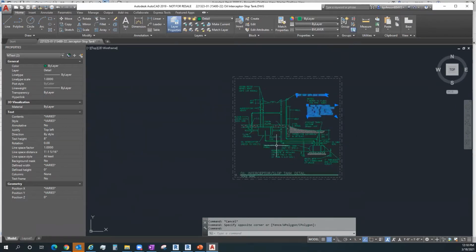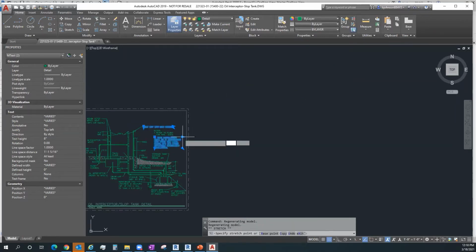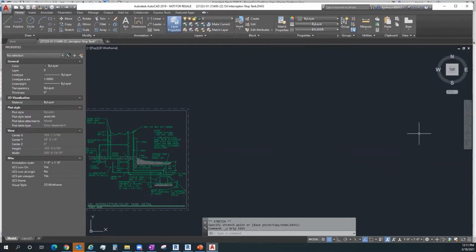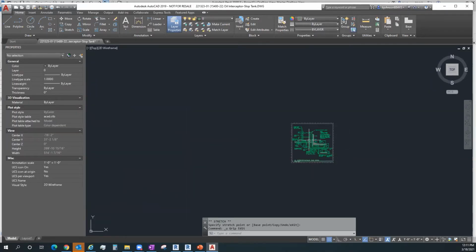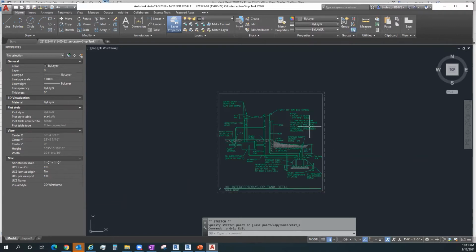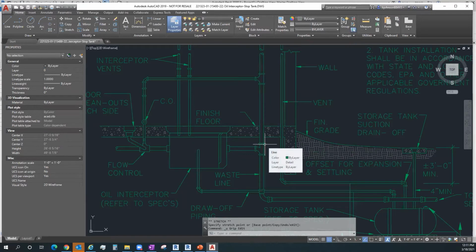Occasionally, when I do a conversion of these, I will have in Revit a piece of text like this show up with the extents way out here. So even though it's just the four lines of text that are still paragraphic like they were, I'd have a text box window that's way, way far over there, and it's not something I want to have to deal with. So rather than having to deal with really weird text boxes, I will usually explode all my text that is M text. And if I have any specialty hatch patterns or something that I know are not going to transfer for whatever reason, I'll typically explode those as well and turn those into line work inside of Revit.